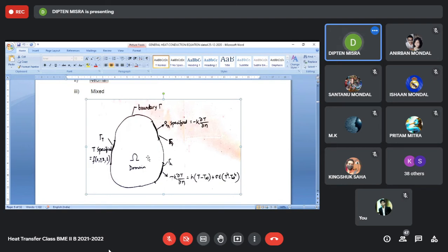So it is actually the condition of the boundary that makes a problem distinct, because all conduction problems can be solved by taking the most general governing equation, that is, del/del x of (kx del T/del x) plus del/del y of (ky del T/del y) and so on, with kx, ky, kz, and those in turn can be temperature dependent.